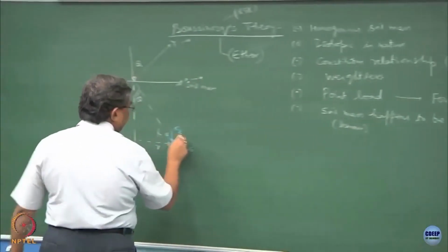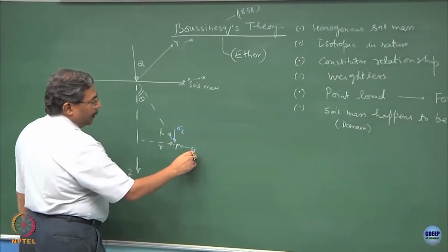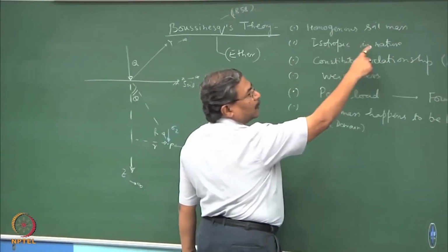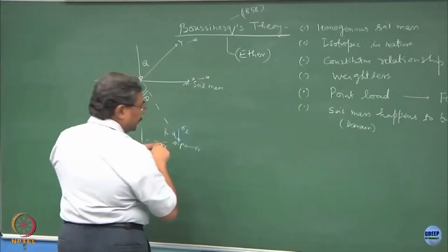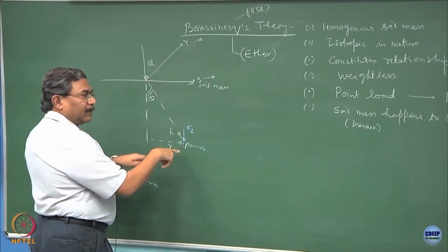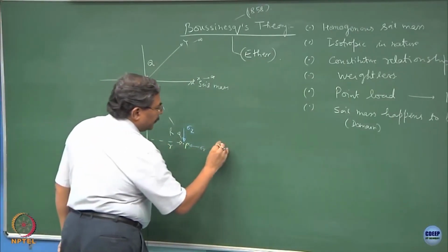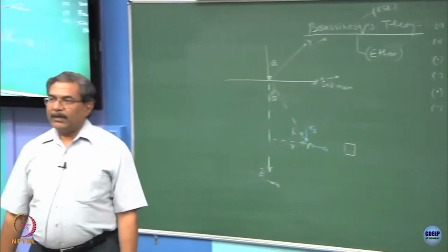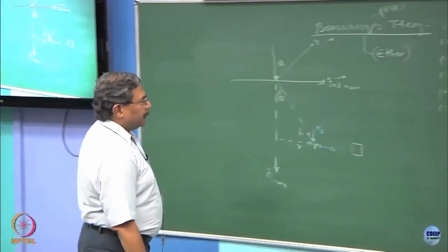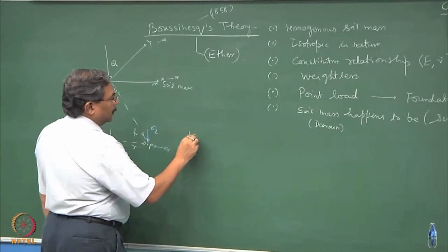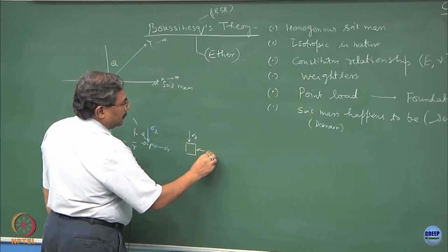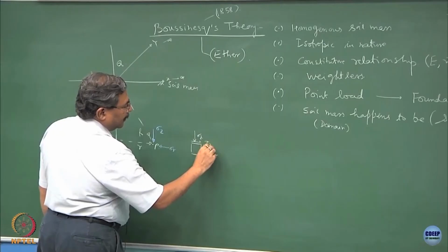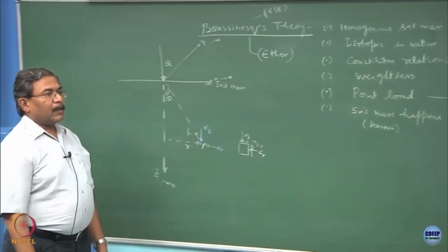So, these are the hoop stresses. So, we have sigma z, we have sigma r. There could be a stress in the y direction also, but because I have assumed this to be isotropic, sigma z is equal to sigma y, clear. If you draw the state of stress at this point, you have done engineering mechanics and you have done mechanics of solids. This is sigma z, sigma r, we will be having the shear stress tau z r, okay.